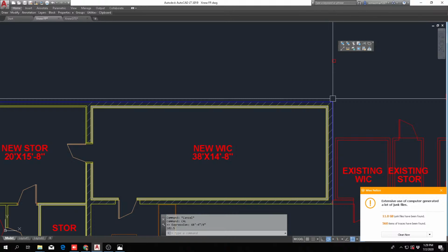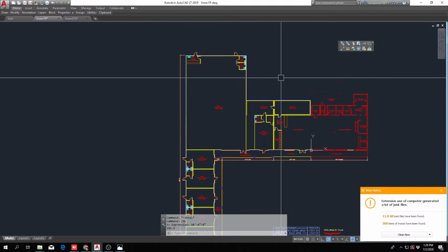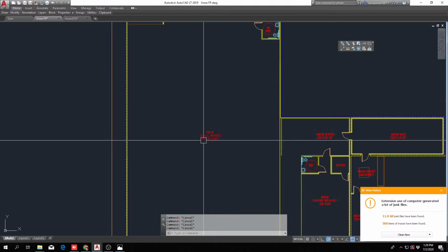You might say, oh, it's a 0.5. It's perfect, because remember, a half a block is a good block. A 3/4 block is not a good block. A 1/8 of a block is not good, but a half a block is a good block. You can use it again. So you're going to have 102.5 blocks. That works out perfectly.